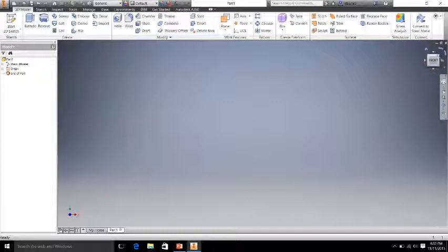But if we take a little bar, if you can follow my cursor, I'll try and do it slow, up to this box, and if you grab a corner and drag, you can change the orientation of your view. So now we can see down here in the lower left hand corner that we have our X, Y, and Z planes. This is the Cartesian coordinate system. It's utilized a lot in this program, and it helps keep us oriented when making our parts.